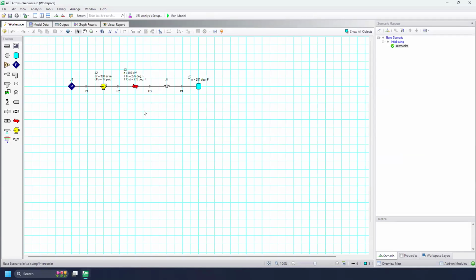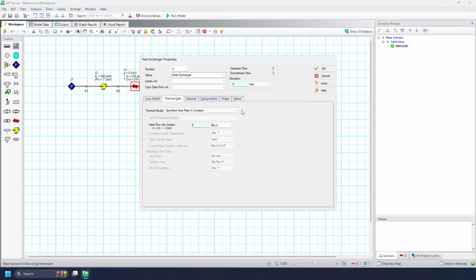And let's say that the air entering this, if it's a machine or supplying the tank, we don't want it to be at over 200. We want to see a rough estimate of how much cooling we're going to need. So now we can change this to the first option here, controlled downstream temperature. Now there's also the ability to do this with stagnation temperature. I will just do the static option, just the first one. Let's say that we don't want this to be over 200.